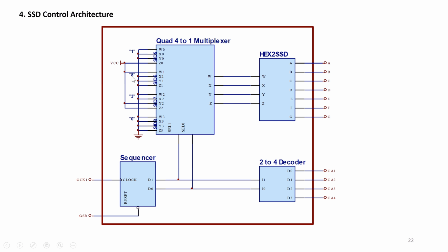For number 8, W is 1, and X, Y, and Z are 0s, as indicated with the ground and voltage source. And notice that the sets of data get fed into your hex to SSD in order to show which data. Now your 2:4 decoder then determines which of your 7-segment displays are powered on.